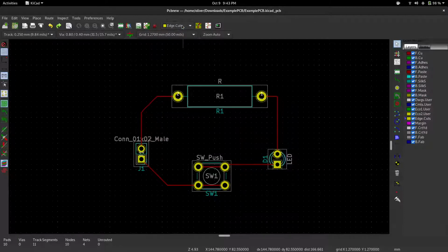The very last step in PCB design is generating Gerber files, which are a standardized file format that you send to a manufacturer that tells them how to make stuff. These layer names mean something. For example, you can actually set where the glue is using the adhesive layer. You can edit the silkscreen layer to change the silkscreen.